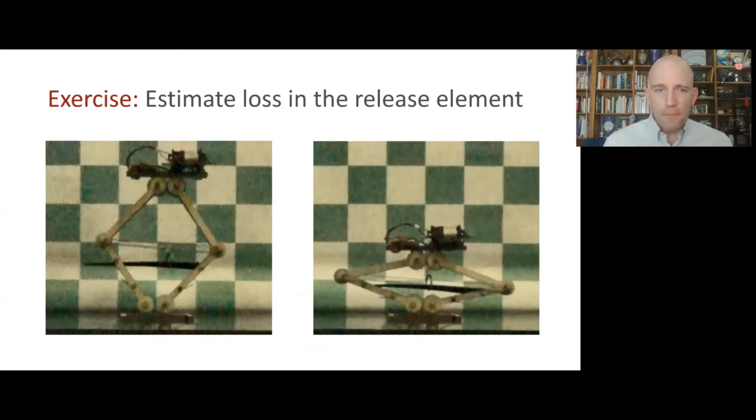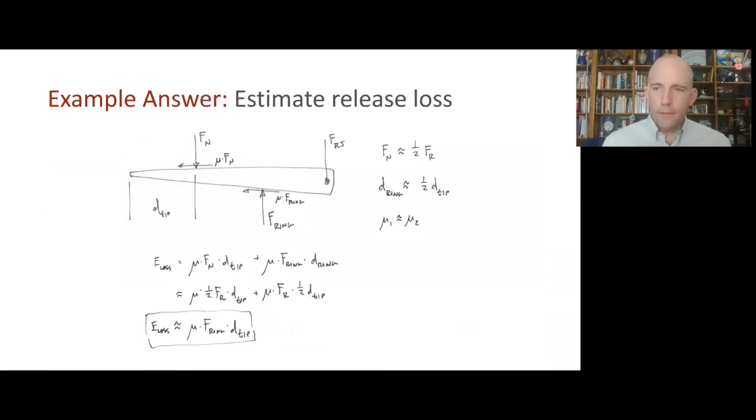All right, did you get something? Well, here's one version of this analysis. So I chose to do a free body diagram of the lever and to try to get at the losses both from the ring sliding along the lever and from the lever sliding along that pin in that one leg. I'm going to skip the energy loss due to this hinge point because the length of the lever is pretty big compared to the radius of the pin over there. So we have this big mechanical disadvantage for the friction, and it will turn out to be negligible in this case.